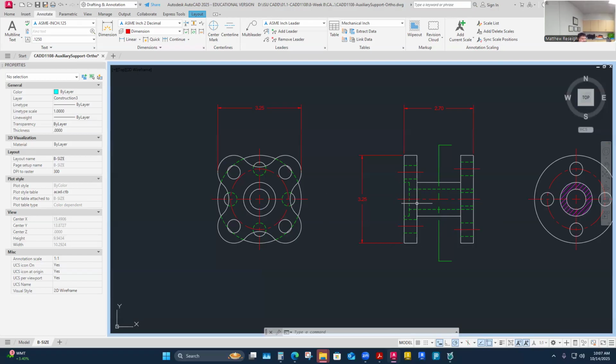So the control for me on this is going to be center marks and center lines or center throughs. It's going to be the best place to establish control. And then the only thing I might need to do in the future is establish how true that axis of this cylinder is. I need to tell someone, keep that thing straight, and it has to fit within this envelope, or otherwise it's not going to be straight and my dimensions are not going to be right. So anyway, I'm always steering you towards GD&T land as much as I can proactively, and lessening how confusing it is in the future.